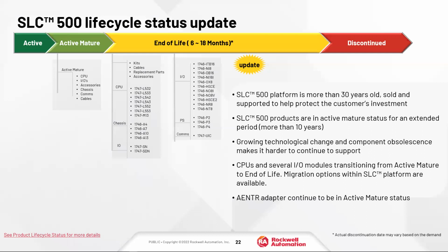Probably one of the most successful platforms that Rockwell's ever introduced. They're everywhere, and so now it's time to move these to CompactLogix. And the same conversion swing arm we have for the PLC 5, we've introduced now for the SLCs. And so we're just starting to do these.